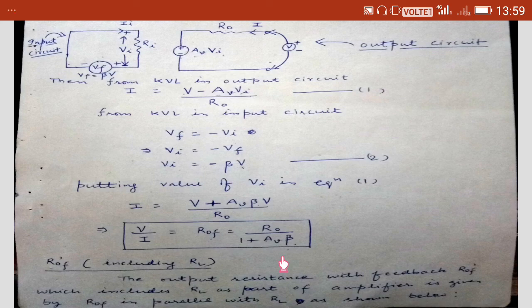Input and output resistance get modified in such a way that they approach their ideal values. Some amplifiers have ideal value of input resistance 0, and output resistance infinite. So in that case, input resistance will reduce and output resistance will increase. This is the advantage of negative feedback.